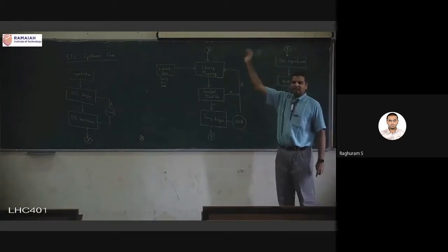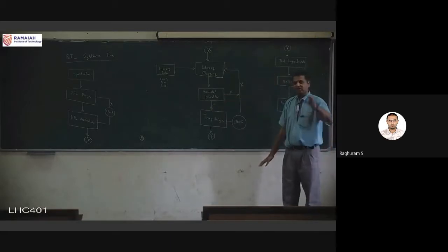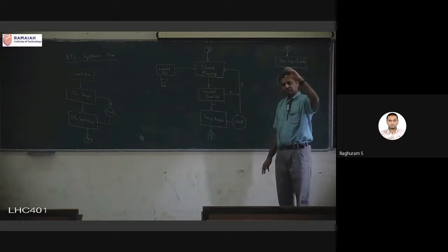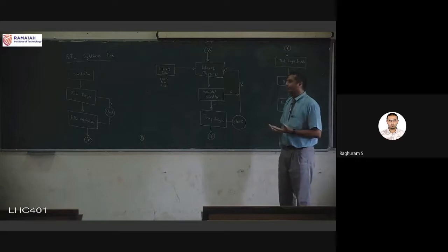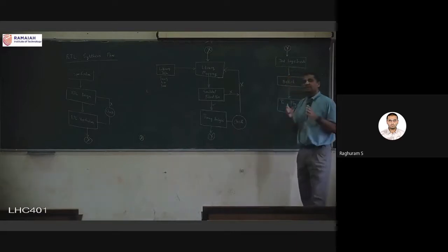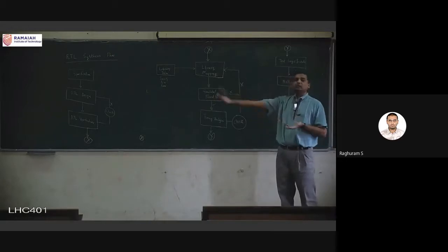It has a lot of analog signal generators, a lot of digital pattern generators, and a lot of hardware circuitry by itself. And it will test that circuit by putting it in test mode, and that might take a few days by itself. Once all that is done, then you know that finally the fabrication errors are also not there. After that, you can go for mass production. Until that, they don't go for mass production.